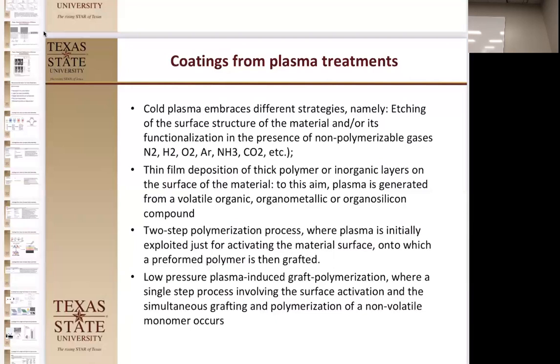But they can also do a two-step process where they plasma first, and then they treat the material. And usually that gives you a better adhesion because then you have controlled plasma on your surface. But you can also use low pressure plasma, which is actually atmospheric plasma. You can actually do it in atmosphere now using radio frequency.